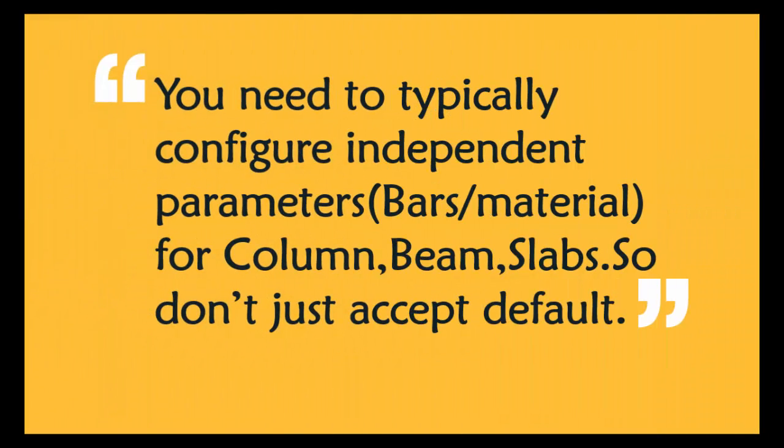If you see this, typically you have to configure independent parameters related to your bars or material for columns, beams, or slabs. So don't just accept the default. You have to know or understand your particular case, material grade, and independently you have to consider this before moving to any further step. And let me show you what I mean by these parameters.